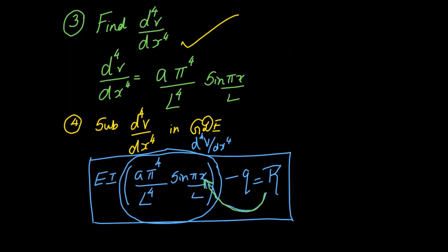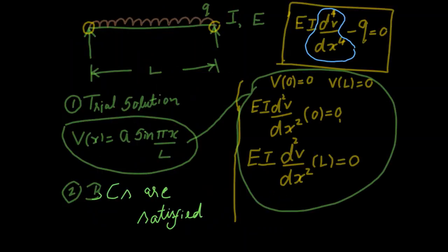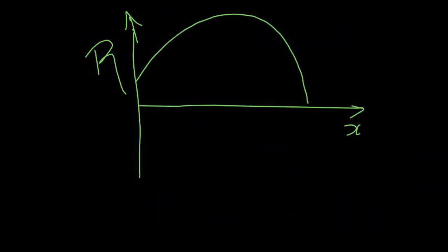I think we have already seen the physical meaning of residual. If you work out the unit on the left hand side, the unit is going to be Newton per meter, which means that residual is something which is error. What has the unit Newton per meter? Well, it is the rate of loading. So we can safely say that residual is error in rate of loading. So there is an unwanted rate of loading that is kicking around. That is the physical meaning of residual as far as this particular problem is concerned.